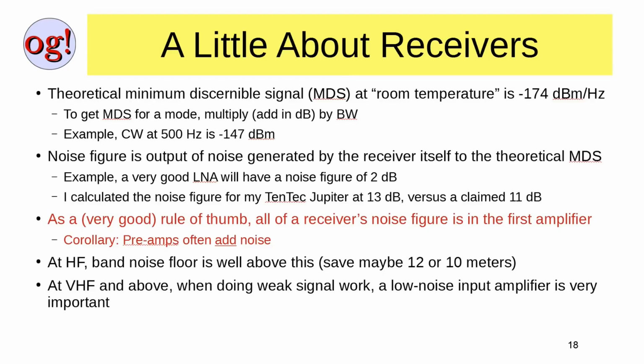Because all amplifiers add a tiny amount of noise. But the thing is, that's important when you've got a tiny amount of signal. So if you've got a tiny signal and tiny noise, you add the two together and multiply that, now it's not so weak. So the next amplifier is seeing a stronger signal and then adds a tiny amount of noise. Not going to make any difference. You go further down the chain and you're dealing with volts instead of microvolts. And the microvolt that amplifier adds in noise just isn't going to make any difference.